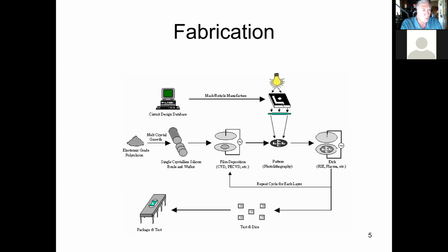The masks are used, and there are multiple patterns on this thing. The photomask just has the one circuit, and it's moved around on the wafer to create the pattern in a whole bunch of different places. There could easily be several hundred chips on a wafer, and they're all created at the same time, which is partly how they reduce the cost a little bit.